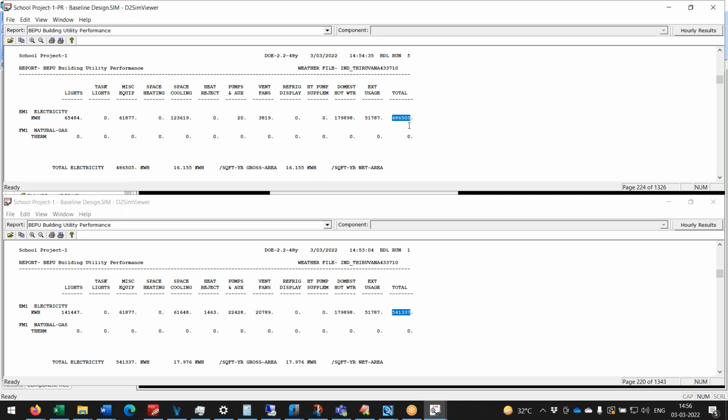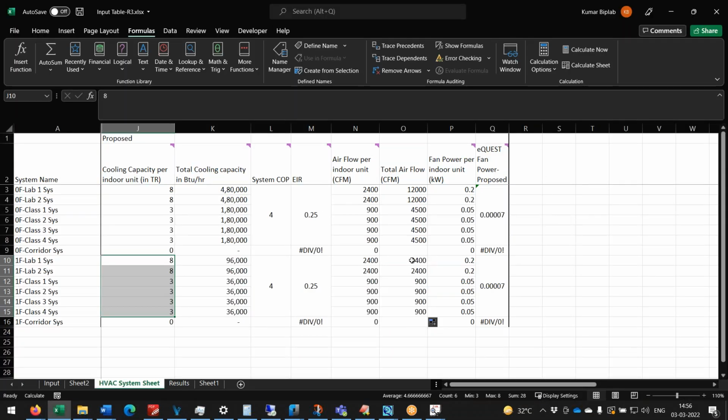So in this case, your recommendation will be to just apply high albedo paints on the roof, or the other option will be to slightly, as you can see over here, the top floor, you see is similar to the ground floor and middle floor also, which is not the case.